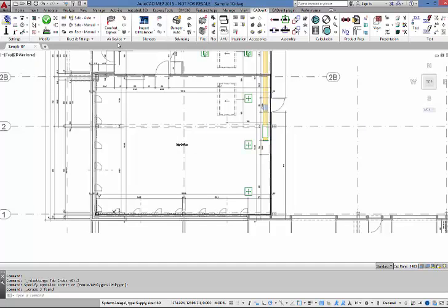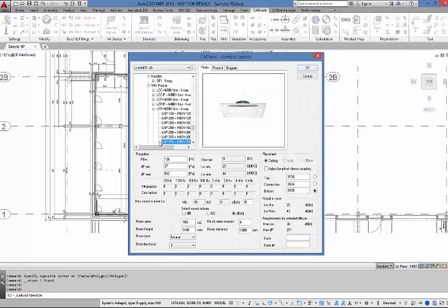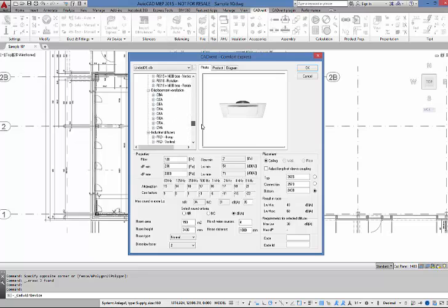Jumping back to CADvent on AutoCAD. Now I use our Comfort Express. That is the selection area for diffusers. I just jump in and say, okay, we have here a selection of all the different types of diffusers in the Lindab product range. In this case, we go for VAV Pascal solution, and we have selected LKP MBBV box in size 315 with a 200 millimeter connection. This one, 120 liters per second.